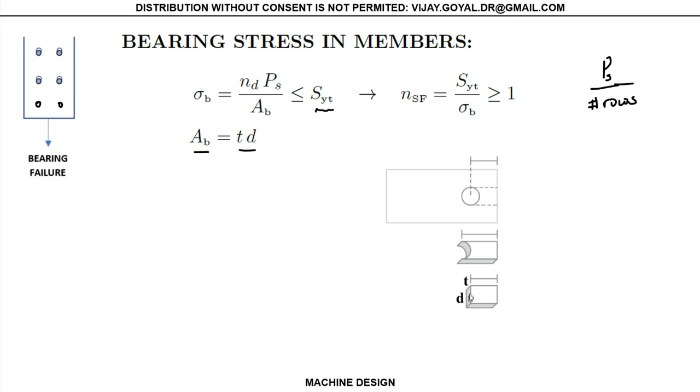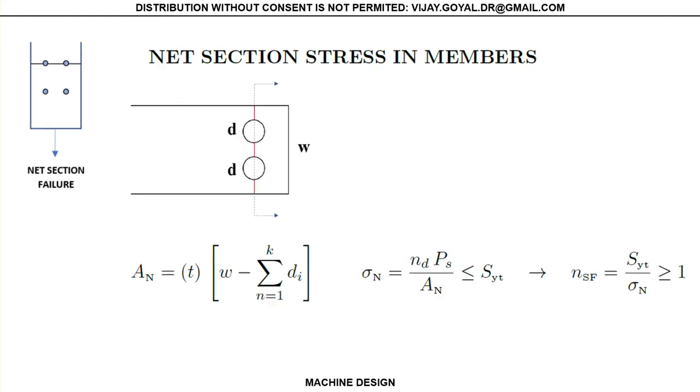So it's the cross section value that we are really interested in. Okay, this cross section, this value right there. Okay, thickness times the diameter. So I have the diameter, this is D, and the thickness that goes inside the plane. Okay, and that would give me a factor of safety for this, and that has to be bigger than 1, because remember I only included 1.15 here.